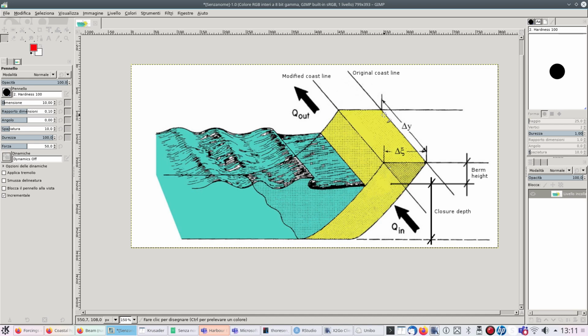So it's sediment transport entering. It may be positive or negative. If it is positive, it means that there are solids entering the piece of coastline. If it is negative, it means that there is erosion. Okay? And then you make the same computation for the next piece of coastline.